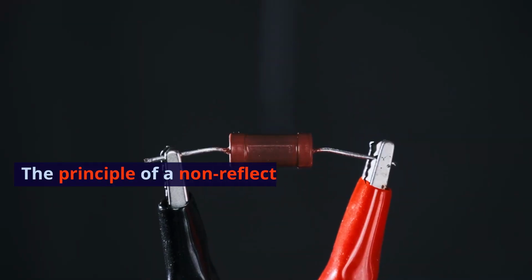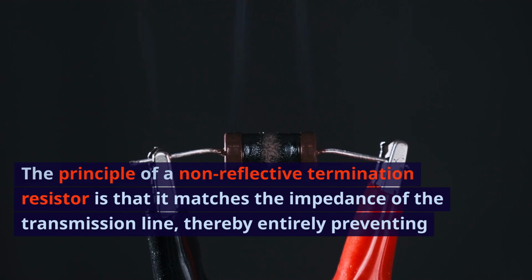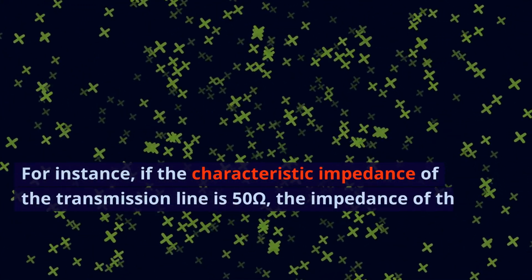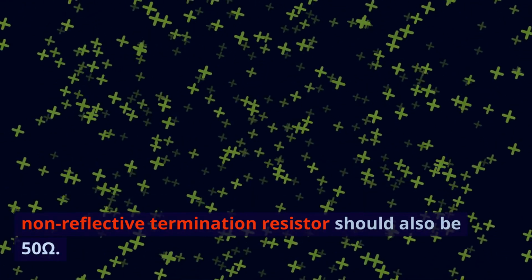The principle of a non-reflective termination resistor is that it matches the impedance of the transmission line, thereby entirely preventing reflections. For instance, if the characteristic impedance of the transmission line is 50 ohms, the impedance of the non-reflective termination resistor should also be 50 ohms.